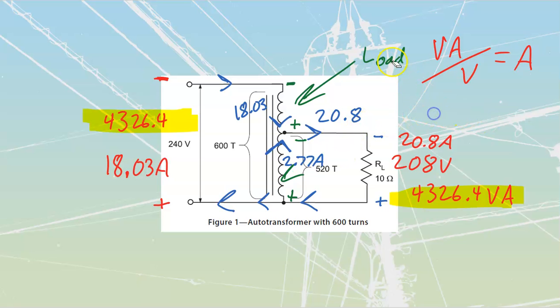KCL works out on this one. All right. Good enough. We've got that thing done there. Well, actually, hold on a second here. 2.77 amps that I have inside of here. The actual rating of this transformer itself would be a little bit smaller. It is an autotransformer connection. In reality, this could be a separate winding that they've connected in.